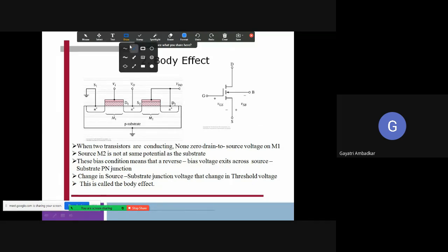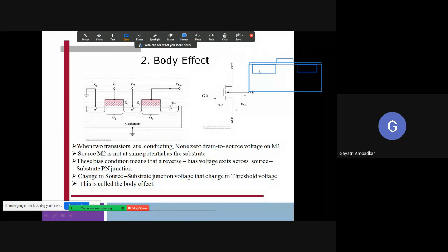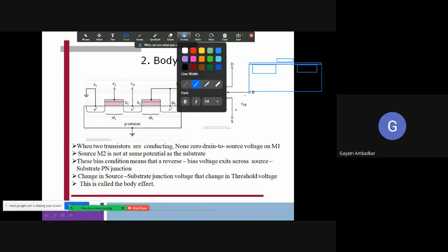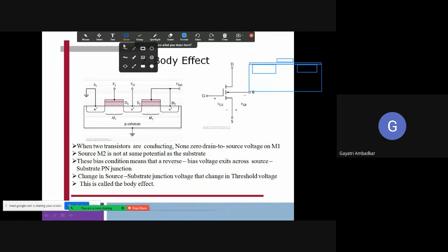So we have seen the construction of MOSFET: first of all we have some substrate. Within that substrate, we have the source and the drain. There is also a gate, and above this there is an SiO2 layer as well. These things you know. Whatever we have seen is the construction of a single MOSFET. I will not draw it again. This is the gate, these terminals taken out are drain and source, and there will also be a body terminal, which we always connect with the substrate.